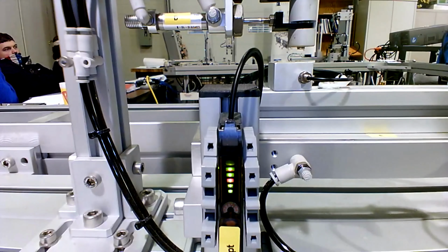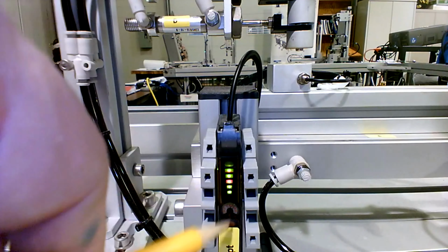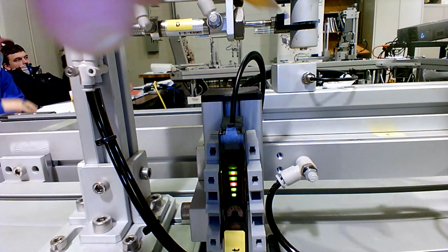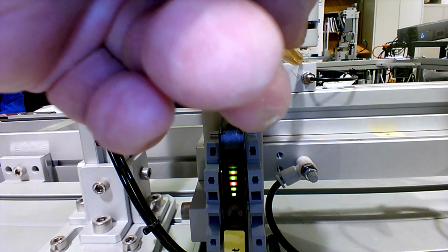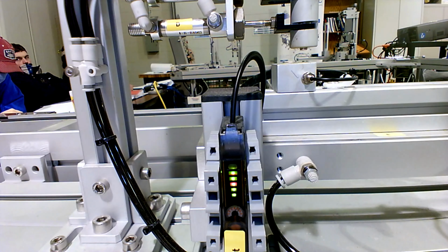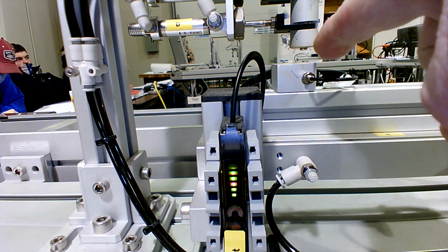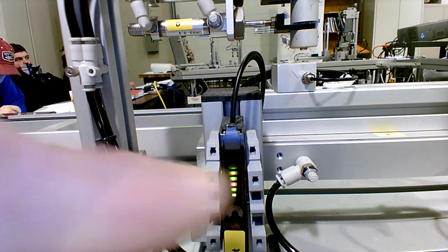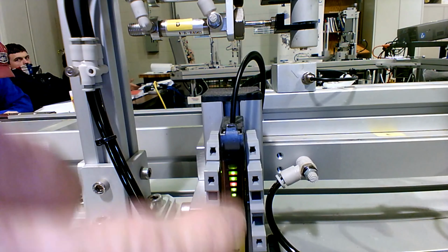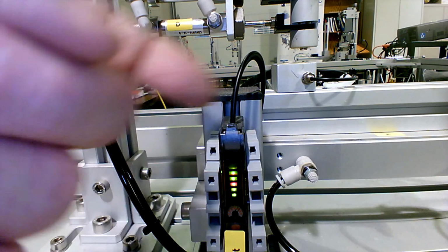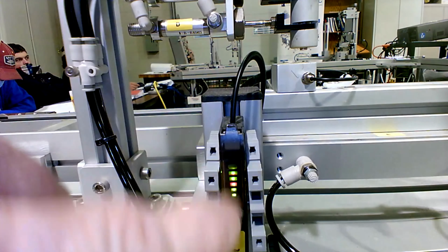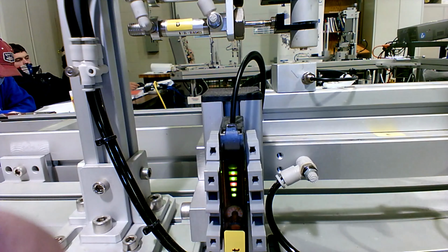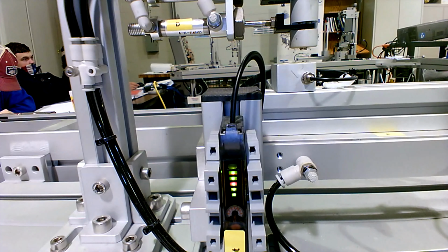Now, watch it closely. When I let it drop a screw, you're going to see the LED indicators change when you see a screw get dropped into there. You ready? So just watch the lights, watch the screw when it drops, and you're going to see the indication on the module. This is a fiber optic pickup module that sends the light out of one hose, and it looks for it coming back, and there's a relay in here. The relay goes to the PLC. Okay? Everybody see what I'm saying?